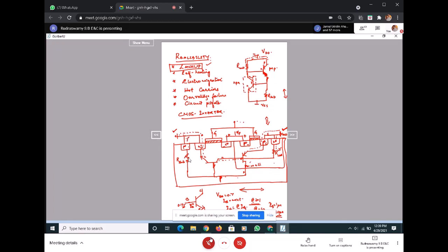Okay, yeah, this resistance should be minimized, and this resistance should be minimized. The moment I minimize these things, I won't be having a connection between the VDD and VSS. This is nothing but a short, right? More power dissipation, more heating.